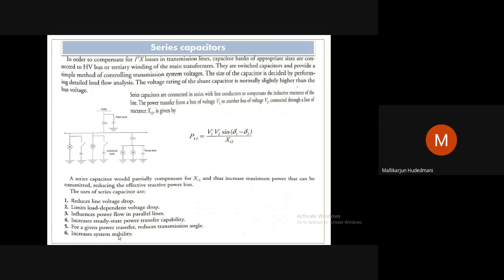So it increases the system stability. Stability of a power system is the ability of a system to stay in service even after encountering any fault, disaster, or any specific adverse situation. That ability concerned with voltage will be stronger if incorporation of a series capacitor to compensate works out. So in this way, a comparison of series and parallel capacitors can be taken up.